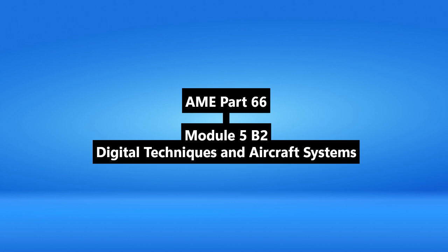Gotcha. Okay. What about BCD, binary coded decimal? Is that just another way of writing binary? Not quite the same as standard binary. It uses binary digits, yes, but with BCD, each decimal digit gets its own 4-bit binary code. Oh, okay. So if you take the decimal number, say 82, in BCD, the 8 is represented by 1000 and the 2 is represented by 0010. So you'd write it as 1000 0010. I see. So it keeps the decimal structure almost. Exactly. You don't treat it as one big binary number with place values across the whole thing. Each decimal digit is separate. You might find it in maybe some older display systems or specific interfaces where that direct decimal link is useful.